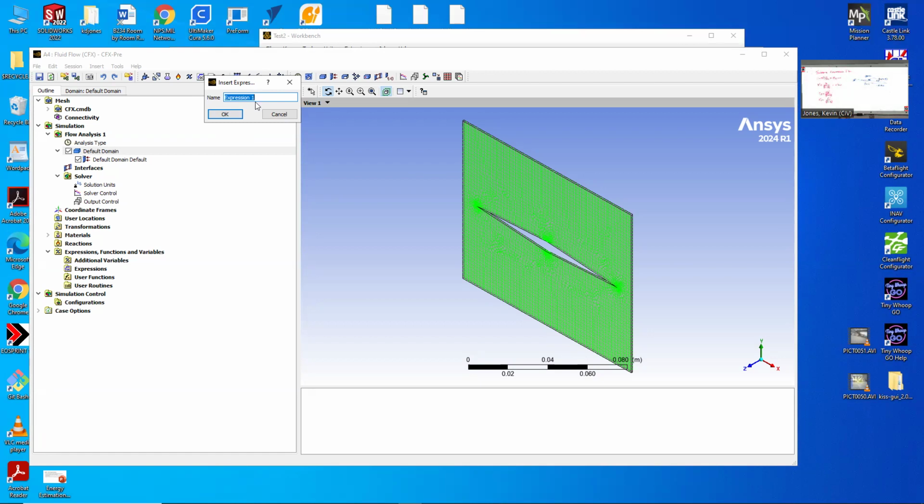We actually want to be able to put in the Mach number and calculate the velocity from that. To do that, we need to know the local speed of sound, which is the square root of gamma R T. That means we need gamma and R. It turns out they don't tell you what gamma and R are. They treat them as variables. But if you remember, gamma and R come from specific heats, so we can kind of force it to do what we want.